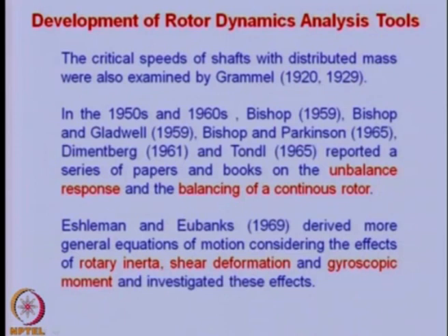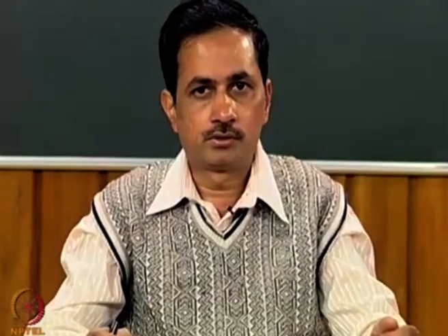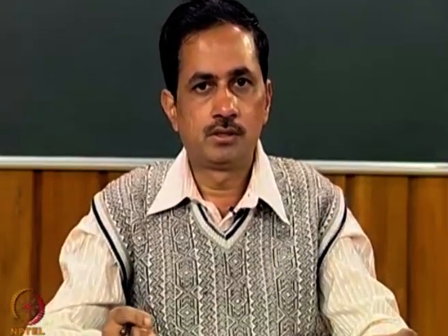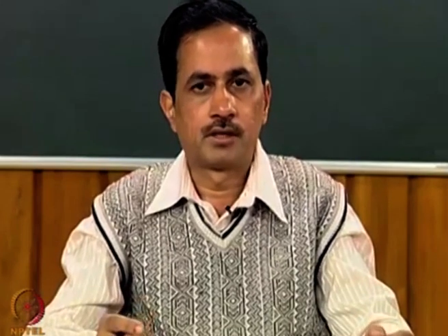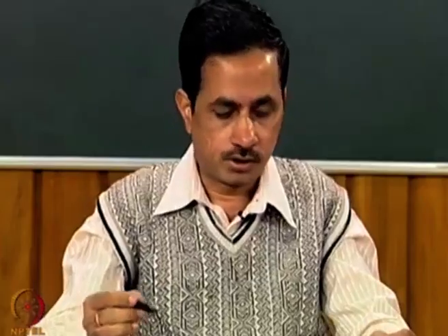Eshleman and Eubanks in 1969 derived more general equations of motion concerning the effects of rotary inertia, shear deformation and gyroscopic moment, and investigated these effects. The rotary inertia, shear deformation and gyroscopic effect are generally called higher order effects in rotor dynamics, and we will see, as we go deep into the subject, how these phenomena affect the natural frequency and critical speed of the rotor system.